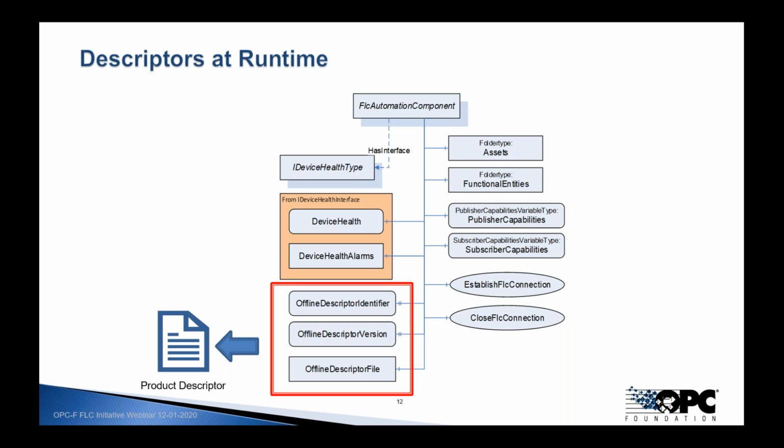So this makes it possible that if an engineer later comes to a plant, gets to a controller, wants to know what is the data, what is the structure of the whole thing, he can just download the offline descriptor from the controller and browse through the structure and start his engineering tool with this data filled. And so he has a better start-up for talking to the online device, than browsing the space and getting the information piece by piece by using OPC UA client server calls.